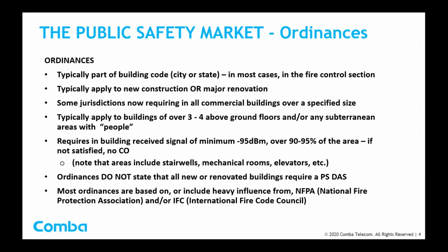But of course, think about the first thing the firemen say: don't use the elevator, go down the stairwells. Well, obviously, if the fire authorities are going to be assisting people to exit the building, they want the radios to work in the stairwells. Typically, ordinances do not state that all new or renovated buildings require a public safety DAS. Very important to understand that. They do state that the building must successfully pass two-way radio communications, and the way we build buildings today, they never do. So pretty much it does mean that most buildings will require an in-building system.